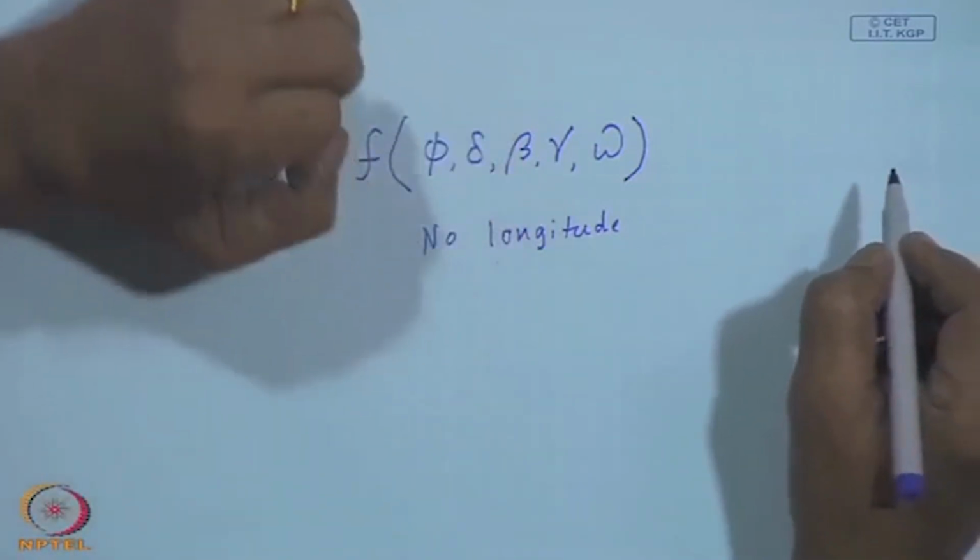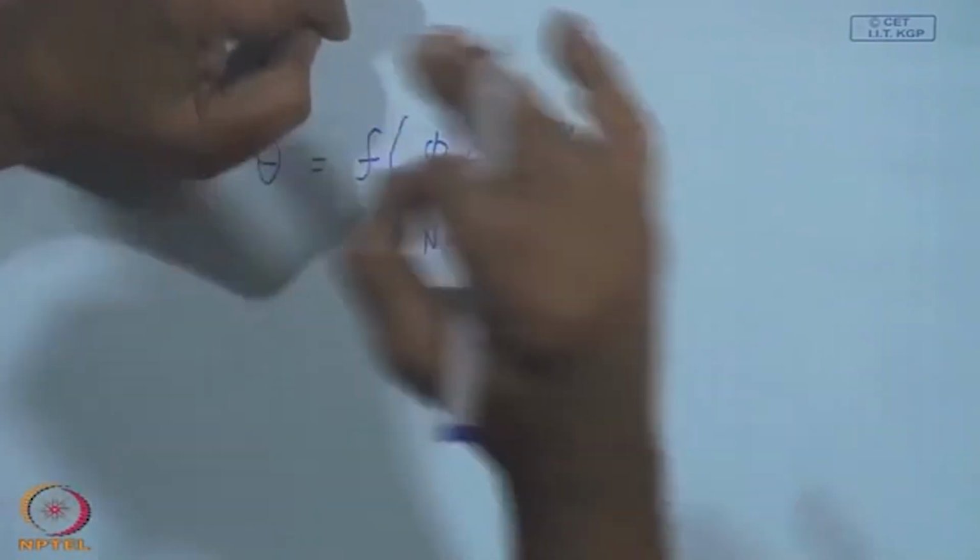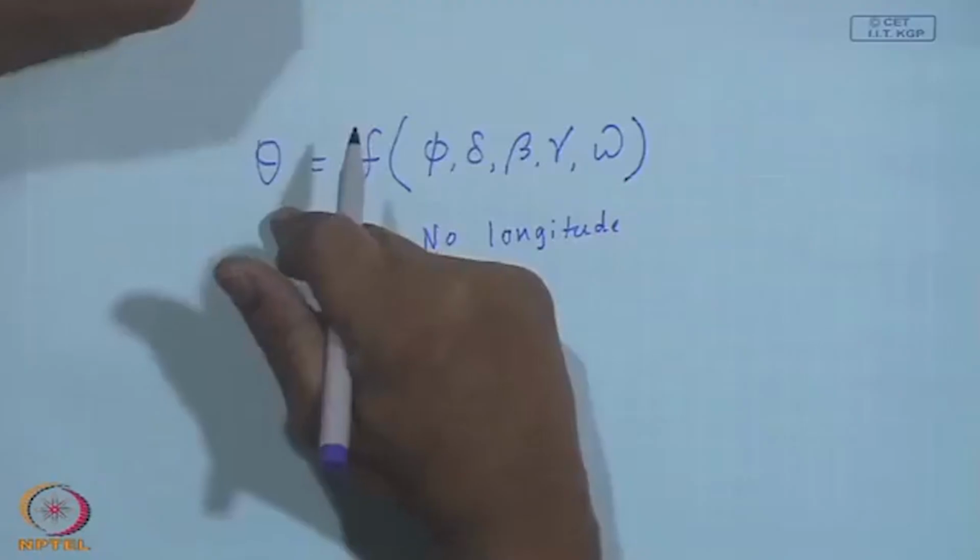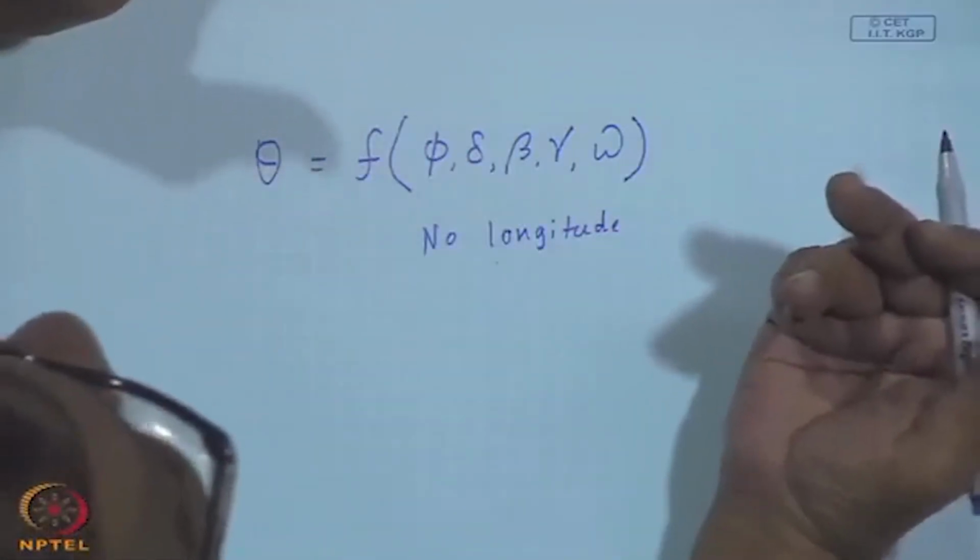It does not depend upon the longitude, because if you are at a particular longitude, another longitude will occupy exactly the same location after the earth has rotated by 1 hour or half an hour or whatever is the time. So, once the hour angle in terms of the sun for that location is specified, the longitude will not influence the angle of incidence. In other words, all same latitude locations will experience the same angle sooner or later depending upon the sunrise and sunset.